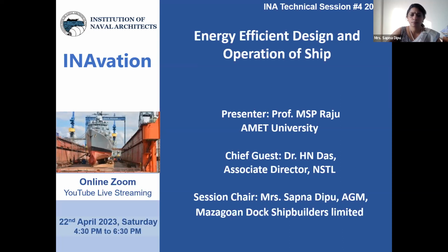Another thing is regarding the SEEMP. That is basically operational, not in the design. Another thing is the fuel. Of course, newer fuels are coming. That is another big story. Another thing is people are asking how they can improve. But as I said, EEDI is a no-wave condition. Now, suppose you have an energy efficiency device which is useful when you have wave conditions, but not useful in normal calm water conditions. It will not help you in actually getting the EEDI, but it may help you in improving your CII rating.